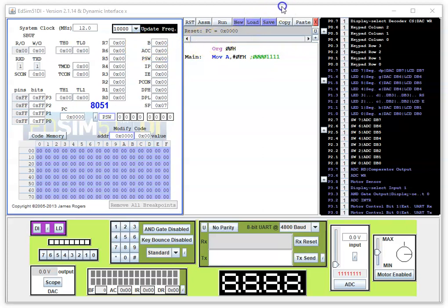All right. Now the next line, we move on to the next line and we type in MOV space capital P1 comma A. What this instruction would do is copy the contents of A. The contents of A at this point is this value, because we said earlier to copy this into A, so the contents of A would be 0F.